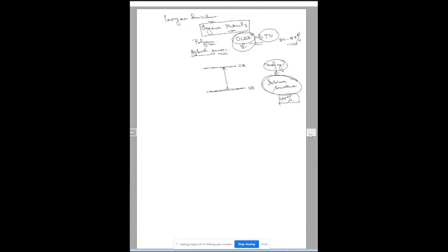If there is an impurity, it may give an energy state in the forbidden gap, which will correspond to the energy level of that particular impurity. Right. Now, in these semiconductor materials, it is possible to put in some impurity deliberately. There is also impurity which can come because of imperfect manufacturing of the material. Some material, say iron or aluminium, comes in because of some imperfection in your manufacturing process. That can give you an energy state in between.